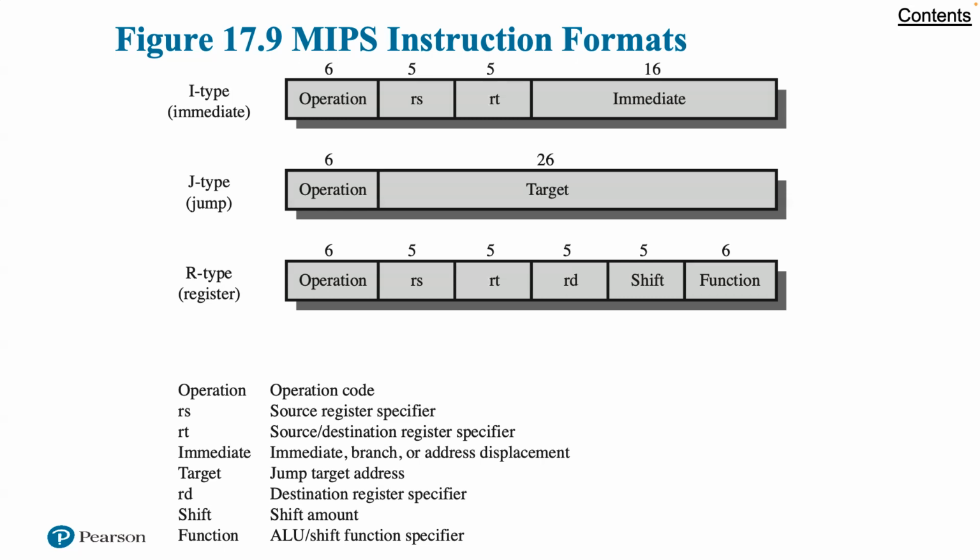The R4000 makes no use of condition codes. If the instruction generates a condition, the corresponding flags are stored in a general purpose register. This avoids the need for special logic to deal with condition codes, as they affect the pipelining mechanisms and the reordering of instructions by the compiler. Instead, the mechanism already implemented to deal with the register value dependencies is employed. Further, conditions mapped onto the register files are subject to the same compile time optimization and allocation and reuse as other values stored in registers.